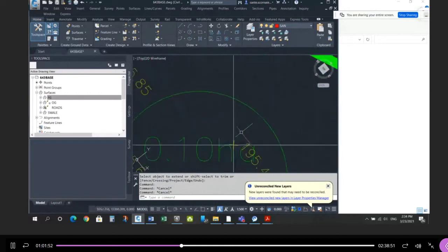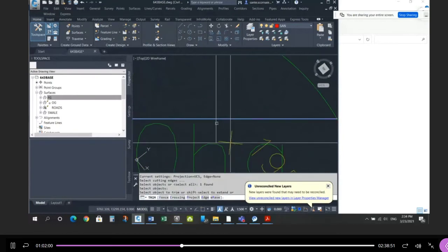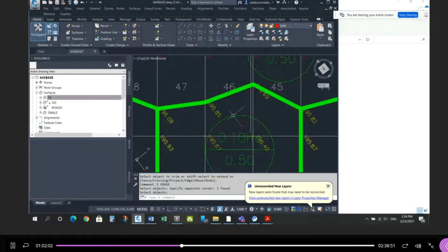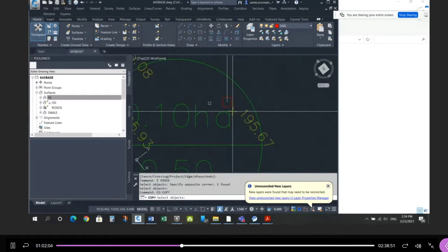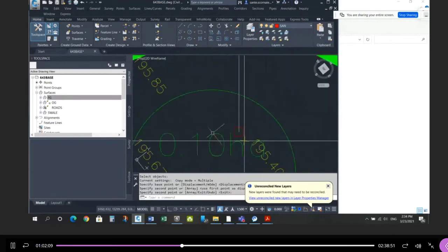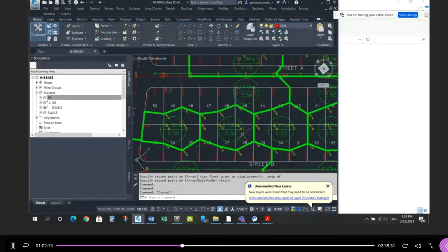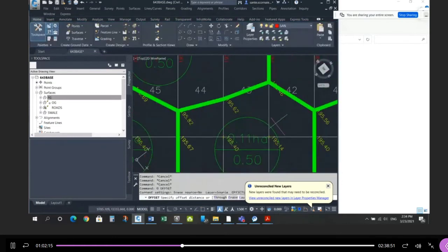Okay, the next low point is right here, so I'm going to offset by 0.6. Offset from the backyard 1 meter, there's the center of the structure. And if these lot lines are all parallel, I should be able to make a copy of this from the end point to the end point. And there's my next pipe. And its design is based on this area, 0.1 hectares, and so on.